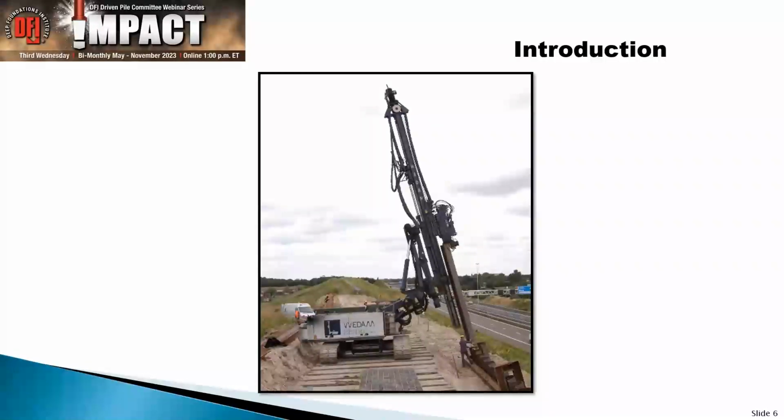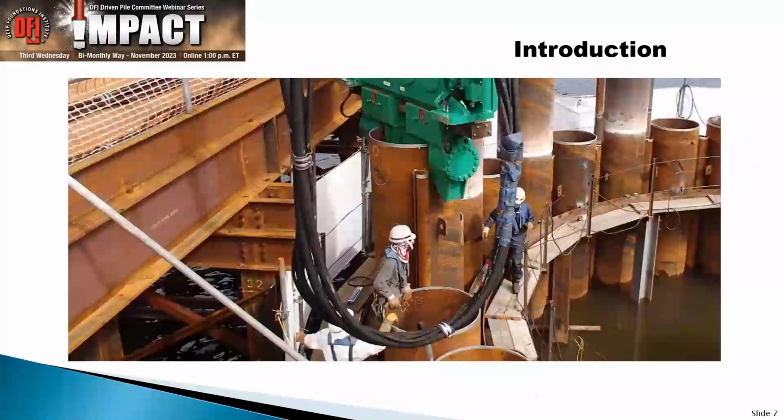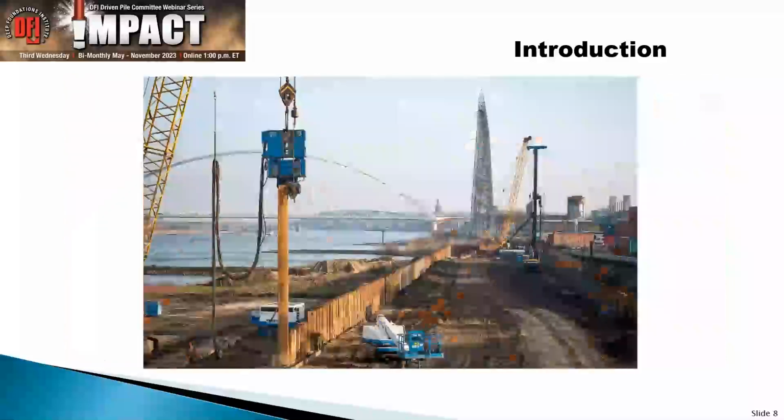So let's talk a little bit about the introduction. What you see here in the previous picture, and again this picture, large diameter piles. And those large diameter piles need to be driven into the ground. And quite often, the vibratory process is faster. But not only that, the piles are getting larger and larger, so that you really need to start thinking about, is it realistic that I can still do this with an impact hammer?